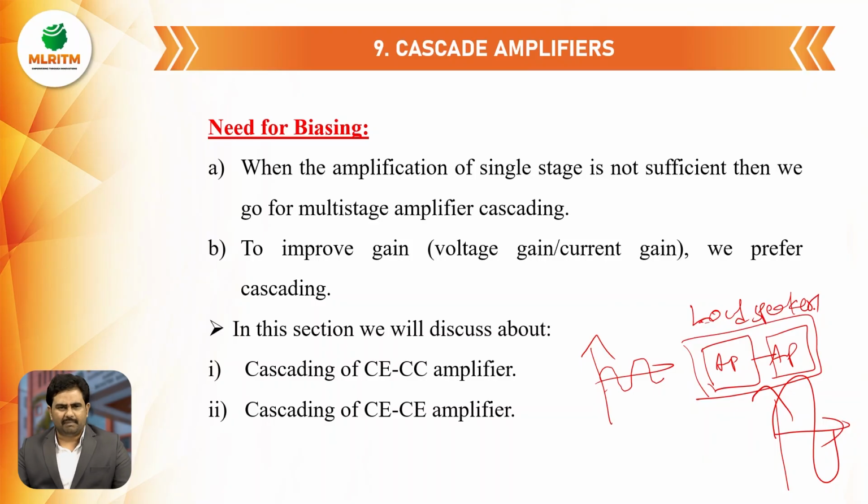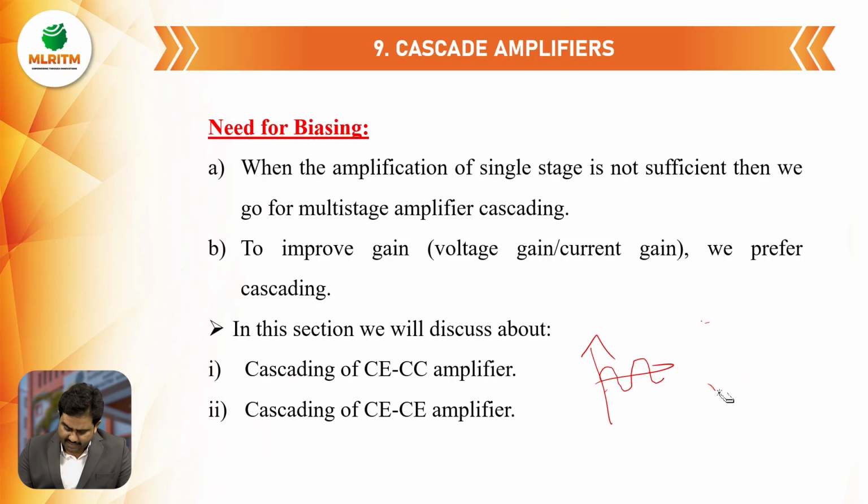So most likely in the public addressing systems, we will use this multi-stage amplifiers concept. Public addressing system means if we go to a bus station or railway station, announcement will be there in which platform, which train is coming, and how much time it will be present in that platform, and all those details will be covered using this public addressing system, right? So in those public addressing systems, we will use these multi-stage amplifiers. Based on our requirement, we are going to connect different amplifiers like CE-CC, CC-CC, like that.